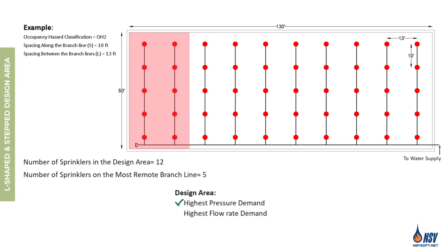To meet the flow rate criterion, we should select the remaining 2 sprinklers that are closer to the water supply, since water experiences less pressure loss along shorter paths. These sprinklers will have higher pressure and therefore discharge more water, helping us meet the required flow conditions.